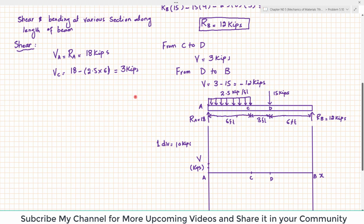Clear? At point A, VA is 18. At point C we have 3 kips, this is 10, so C will be somewhere here. Now from C to D this will be the same because it is uniform, and from D to B this is minus 12, so minus 12 will be somewhere here.